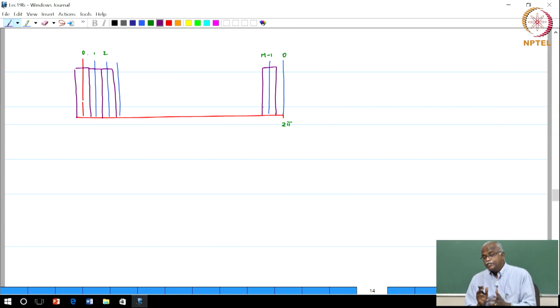Okay. So, what is the OFDM transmitter actually doing? The OFDM transmitter says channel number 0, you please transmit for me symbol S0, some QAM symbol, and channel 1 you transmit S1, you transmit S2, and so on. This is an FDM signal. What would you do on the other end? You would do the inverse operation.